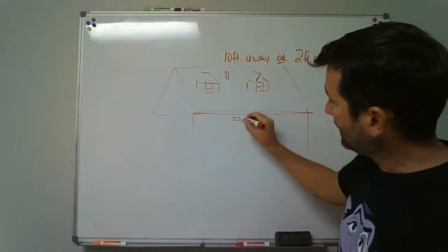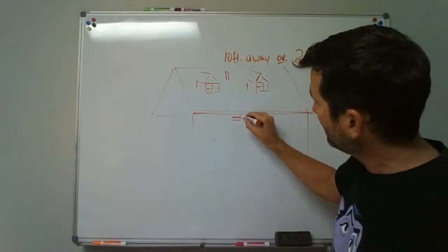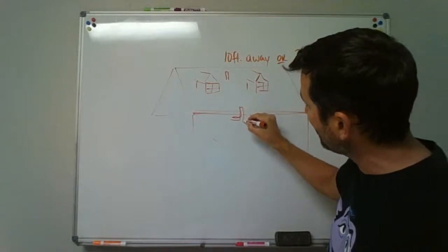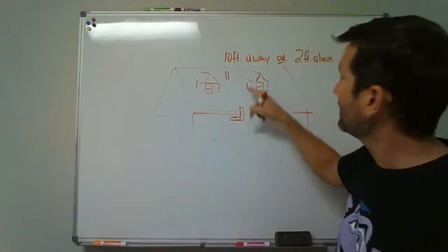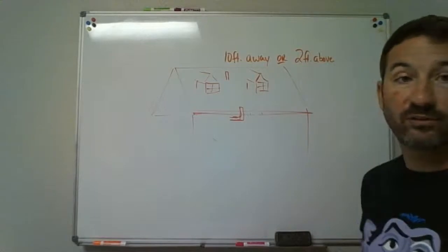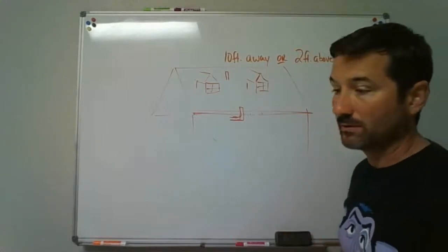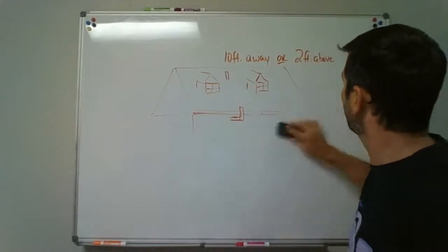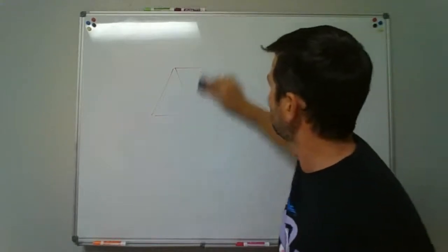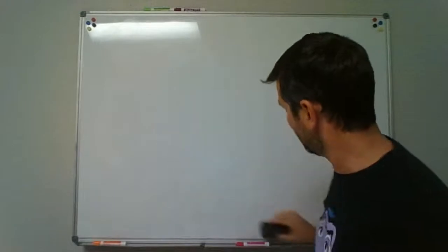But now it could pop out and then maybe turn up above the soffit to where you could get the 2 foot above the ventilated soffit, and then that would work for you. Okay? 10 foot away or 2 foot above on those vent terminals.